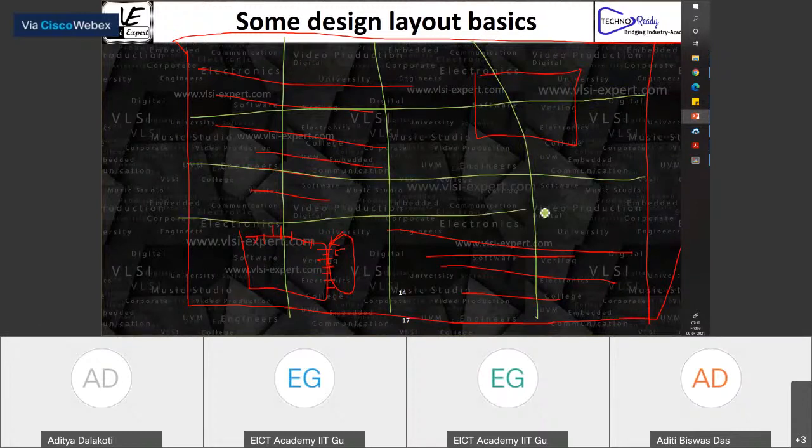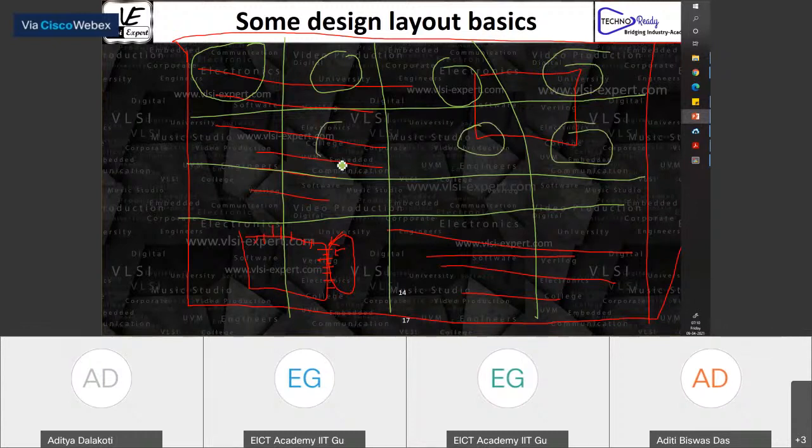And then it will try to figure out: what is the amount of routing resource available to me here? What is the amount of routing I actually have to do here? Can I do all that? With the row and vertical and horizontal track estimation, it knows what the requirement is, what it has, and whether it can do this. It does a global routing approximation. Right now it only does an approximation. Can this be done?